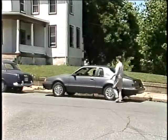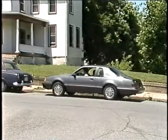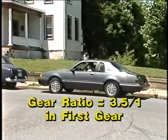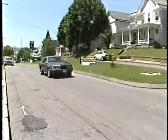The relationship between power, torque, and speed not only describes what occurs across a gear set, but also explains why gears are used to transmit power. Gears are selected for particular jobs based on what the requirements are for either speed, torque, or both at the output of a gear set. For example, the next time you're driving to work, imagine what it would be like if you had to travel the entire distance in first gear. The gear ratio in this car is about 3.5 to 1 in first gear. You'd certainly have plenty of torque, but your top speed would be pretty slow.